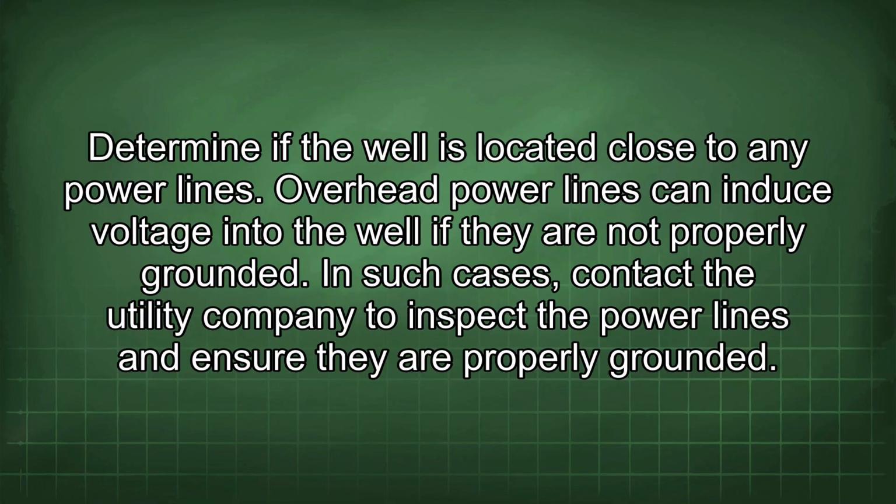Determine if the well is located close to any power lines. Overhead power lines can induce voltage into the well if they are not properly grounded. In such cases, contact the utility company to inspect the power lines and ensure they are properly grounded.